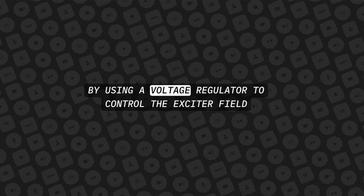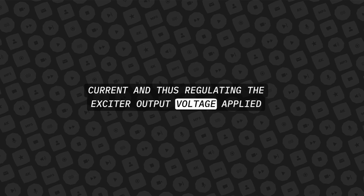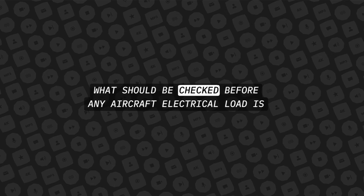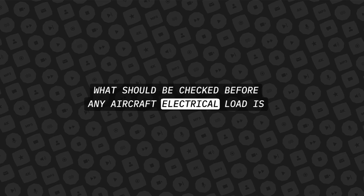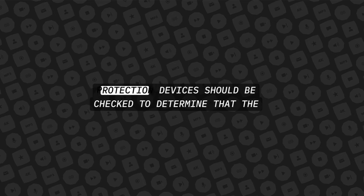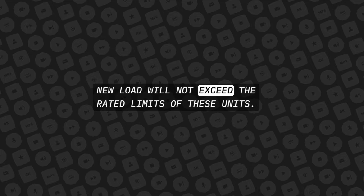By using a voltage regulator to control the exciter field current, and thus regulating the exciter output voltage applied to the alternator field. What should be checked before any aircraft electrical load is increased? The associated wires, conductors, and circuit protection devices should be checked to determine that the new load will not exceed the rated limits of these units.